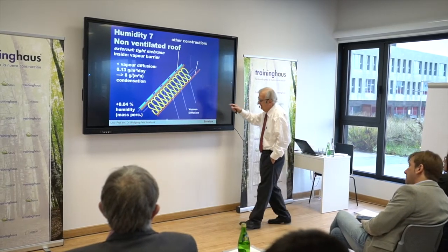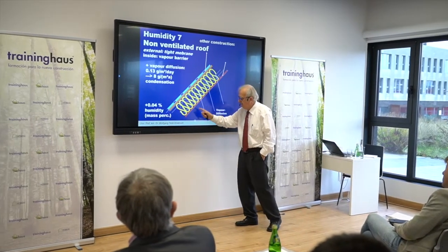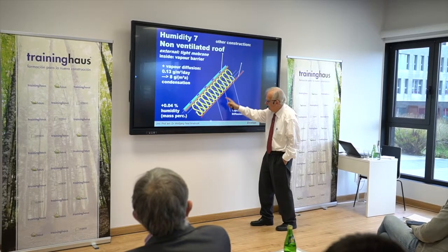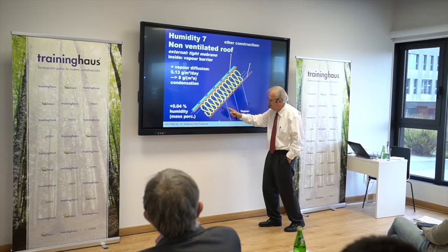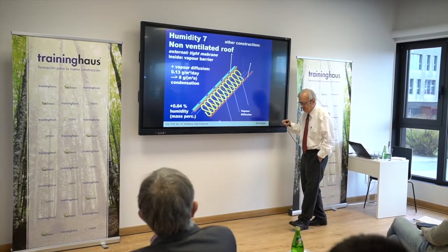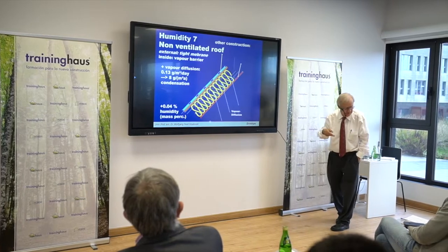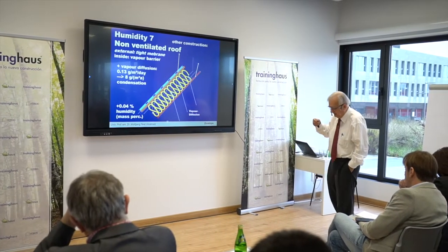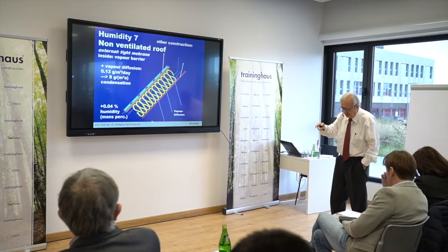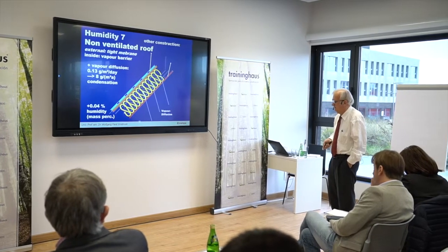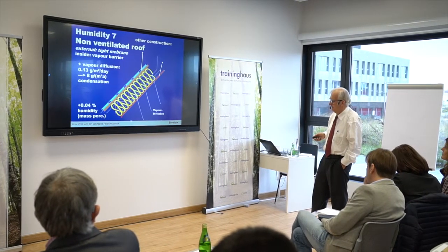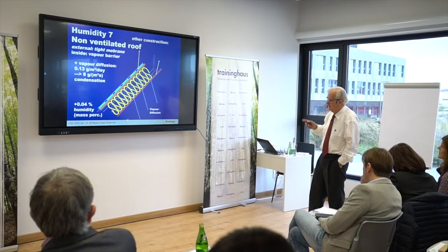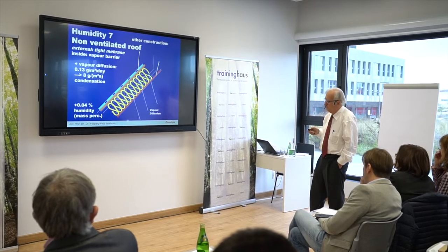What that means is that you need a diffusion barrier here, something which has a little bit higher resistance to water diffusion. That is some film materials which are more watertight than other materials normally used at that point. So the diffusion could be managed as long as it is very low.